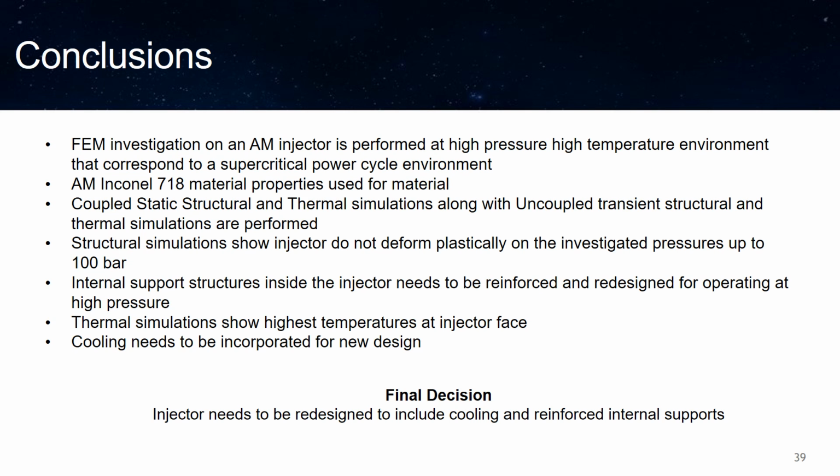For conclusion, we have looked into an FEM investigation of this additively manufactured injector in a supercritical environment, that is, a high pressure and high temperature environment. The material we used was Inconel 718. We did a coupled static structural and thermal simulation and an uncoupled transient structural and thermal simulation.